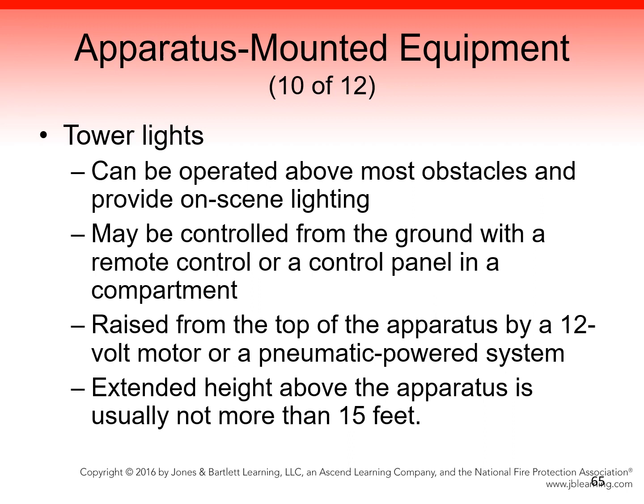Multiple 1500-watt halogen lamps, or LEDs on the newer tower lights, are usually mounted at the top and may provide 360-degree rotation with tilt capabilities. They are also illuminated by a 12-volt light to signal to the drivers that they are in the raised position. Some apparatuses are also equipped with sensors to notify the driver-operator when the tower light is still in the raised position, a factor that must be taken into account when the apparatus is moved.